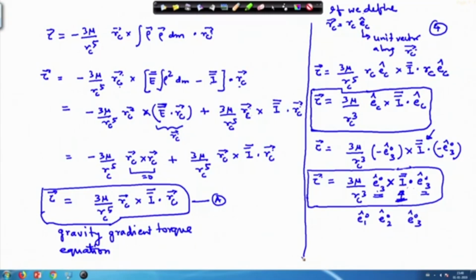And if you do not want to do this, then start from this EC vector, assuming that it was in the inertial frame. We can go to the orbital frame system, and from orbital we have to finally go to the body frame system. But here it so happened that EC and this EO3 cap were directed opposite to each other. So, we have been able to replace, but thereafter going to the body frame we cannot do it so conveniently, and we need to do certain transformation.